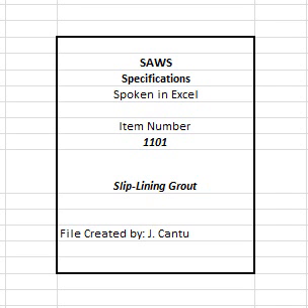2. The application system shall have sufficient gauges, monitoring devices, and tests to determine the efficiency and effectiveness of the grouting work and to provide a means of accurately determining the amount of grout injected. Contractor shall be prepared to modify the operation should grouting not perform as proposed. Such modifications and changes shall be done in a timely manner to avoid unnecessary delay in completion of the project.